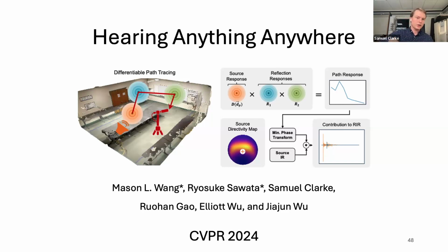If you have a softer object, that essentially acts like a low pass filter on the frequencies. But for the hammer, we didn't have the sounds of the hammer polluting our data to a significant degree. There's going to be a little bit of sound from the handle or something, and also the strike was sharp enough that it shouldn't have dampened out the vibrations very much, but the deconvolution should correct for what little of that may have happened.